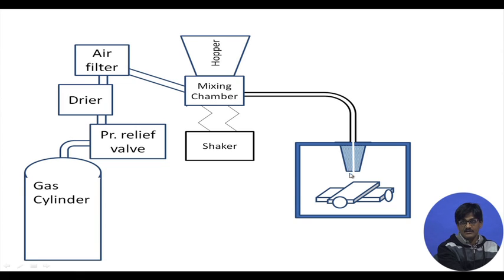If this diameter is slightly higher, it has to be between 0.2 and 0.8, and therefore you will have a negative pressure created here, which will suck in the abrasives through this hopper. The abrasives get entrained into the air, because here there is a very small diameter entry and a slightly higher diameter here, so that vacuum pressure is created.